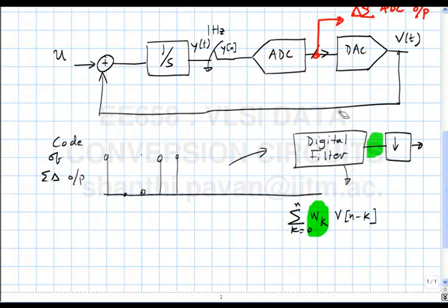Does that make sense? So once the amplitude levels are quantized, you do not need to keep track of a bazillion continuous levels. You need only a finite number of levels, which means that you can represent each of these levels by a unique code word, right? And then filtering simply becomes manipulating these code words. So register length, all the hardware involved in a digital filter is basically gates. Gates, flip-flops, which are basically delays, and you can use gates to make a multiplier, adder, and all this wonderful stuff.